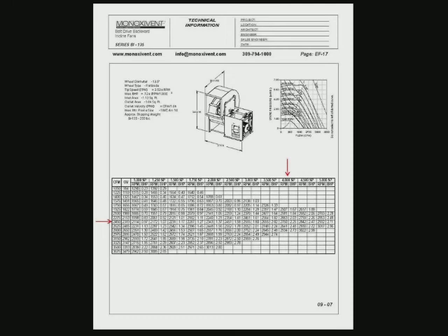Well, with intermittent temperature, I think we're talking about just short bursts of time, seconds, not minutes. If you look at the 5000 series hose, 550 degrees intermittent temperature, we can get it up to that temperature for a short period of time, and then we want to bring it right back down again. That particular hose, if you get over the 550, you will melt the fabric. You don't want to leave it that hot for an extended period of time because it will melt the hose. So when we're talking intermittent, we're talking seconds, not minutes or hours.